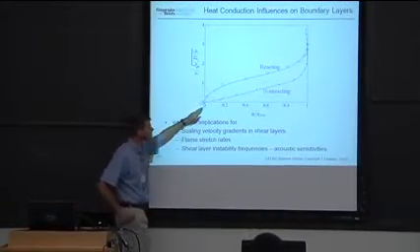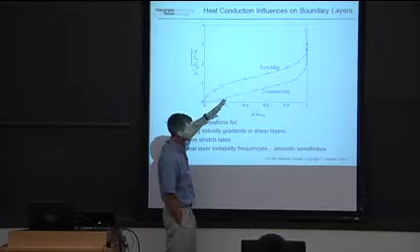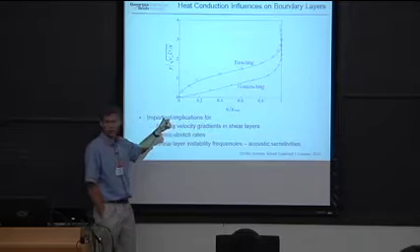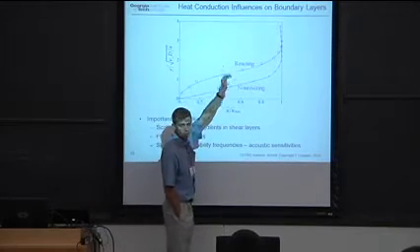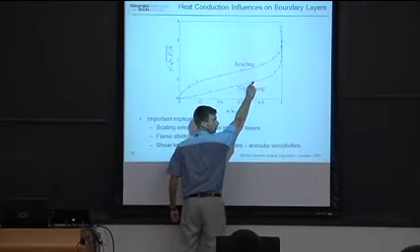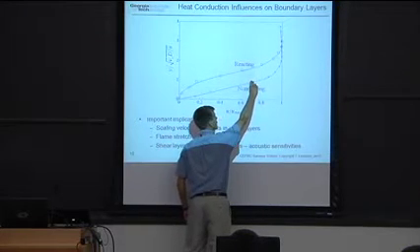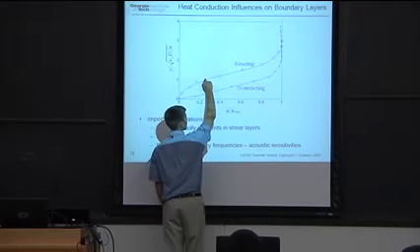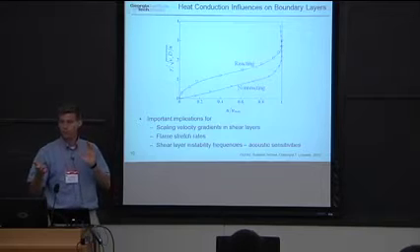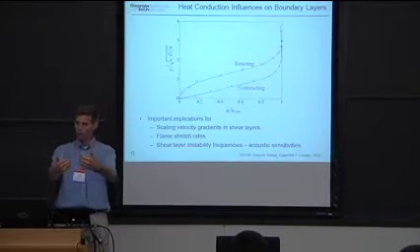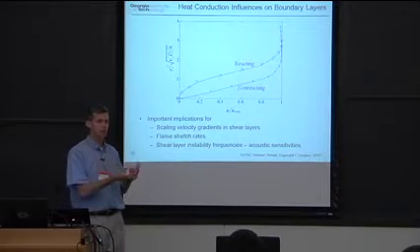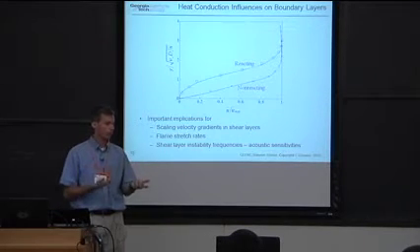And just to illustrate this, this is some data from our lab where we took a non-reacting flow and got a nice boundary layer profile. As soon as we turn on the flame, look what happens. You get this inflection point. The whole boundary layer gets a lot thicker. So if you were saying, well, if my quenching distance is this, my velocity should be this. But look what happens as soon as you turn on the flame. The critical velocity drops to something much lower. And so, again, this points to this hysteresis between flashback and flame holding. Once the flame can propagate upstream and start heating up metal, it has a lot easier time staying there than it would otherwise.